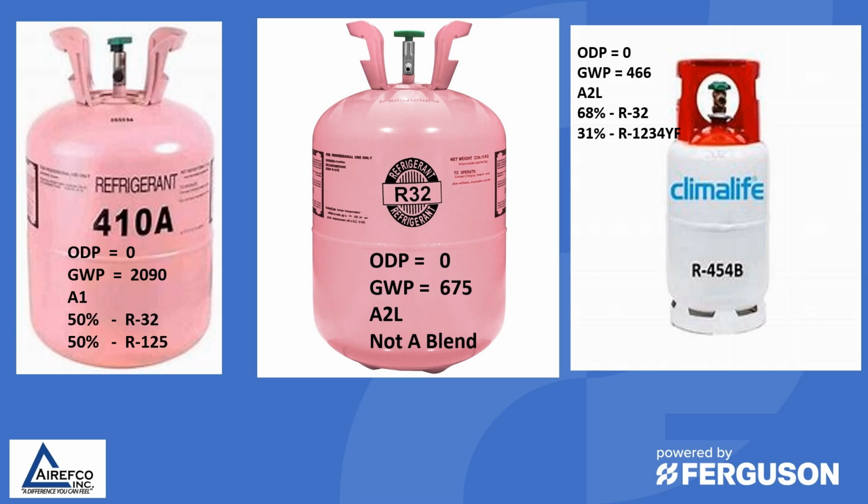454B is going to be the refrigerant of choice for many manufacturers. The reason for that is the low global warming potential. 410A had an ozone depletion potential of 0, global warming potential of 2090, and was an A1 refrigerant with a mixture of 50-50 of R32 and R125. R32 is not a blend.